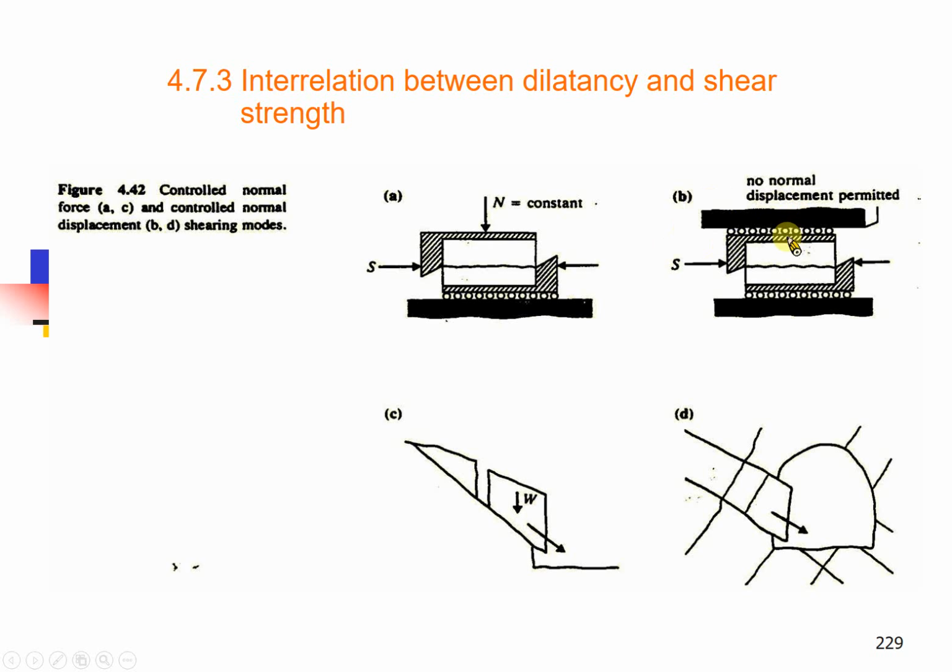The anchor will have its stiffness. Every structure will have its own stiffness. So under that condition, we can try to control the displacement. How to control the displacement? We try to use the servo control system, which can be used to do this so-called constant stiffness experiment. So the rock joint test will be more complicated than direct shear for soil.